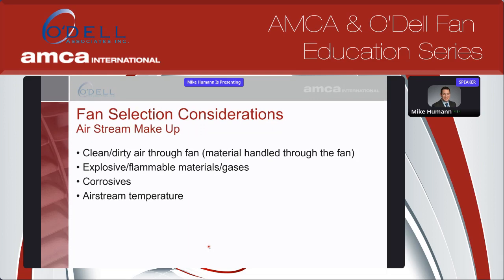Also, are there any explosive or flammable materials or gases involved? That'll be critical because we'll need to know if we need to offer some sort of spark resistant construction or maybe some other considerations to have that fan be able to handle those materials. The same goes for corrosives. You want to know that ahead of time, so we select the right type of fan, but also the right material to handle those corrosives. And last is airstream temperature, and that's really critical for proper selection of materials, but also proper selection of your fan arrangement and type.